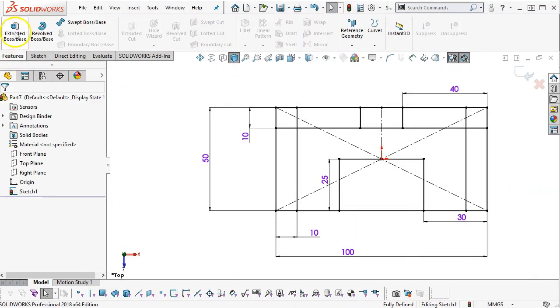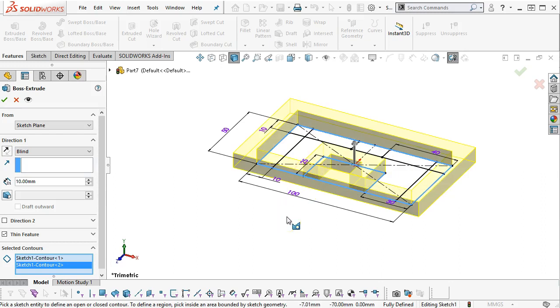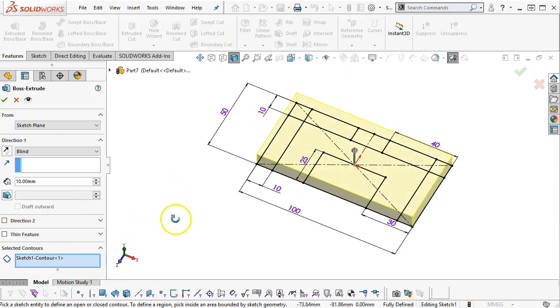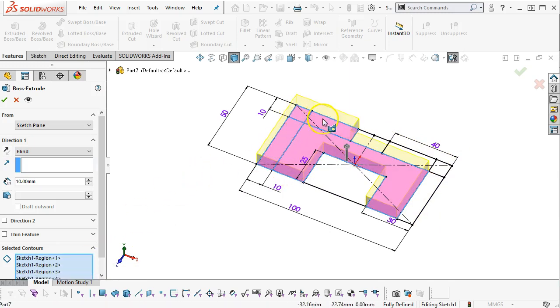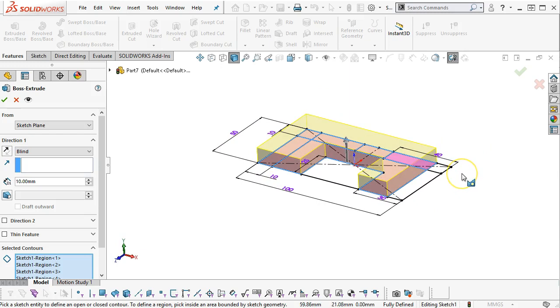All right, so when I go to extrude this, the base is going to go all the way around. All right, if I select, it's going to be a thin feature. So let's deselect, make sure the thin feature gets turned off. All right, so contour is the line, it's finding the connected items, not a best choice. All right, so all of those little lines, I'm going to have to fill in those boxes. So that's kind of a nuisance, but it gets it there. And let's see, the height was 15. And that gets our base shape.